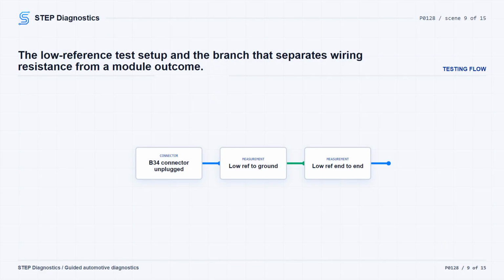For circuit testing, turn the ignition and vehicle systems off before disconnecting connectors. It may take up to 2 minutes for all vehicle systems to power down before an accurate ground or low reference continuity test can be made.